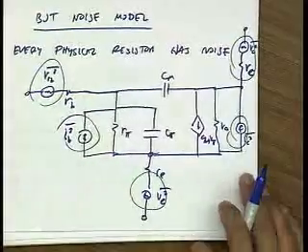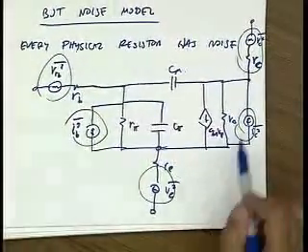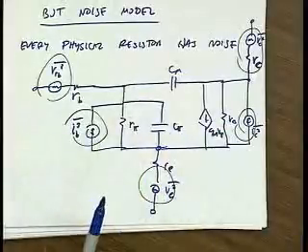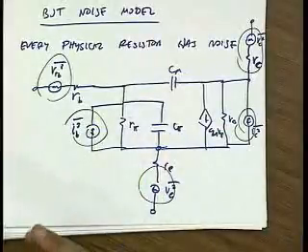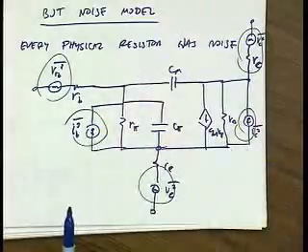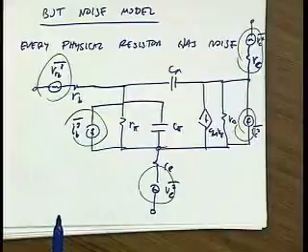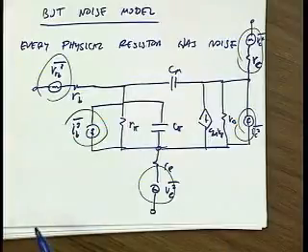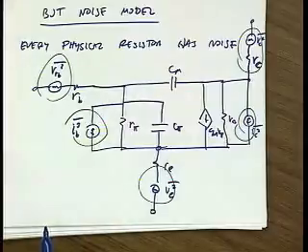And you might say, why can you just use a small signal model? Okay. Well, fortunately, there's one good thing about noise: it's pretty small. So it's small enough that it will only excite the small signal circuit. If you think about noise in terms of statistics, what's the probability that a noise voltage with a certain RMS, let's say of a nanovolt, will reach 1 volt?